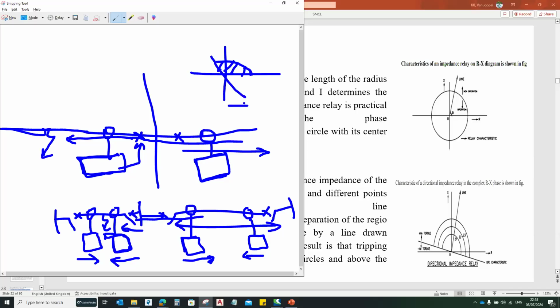The direction element will be set based on your positive sequence values, negative sequence values and zero sequence values. But this curve is starting from the left quadrant. Yes. But the bus is actually located at the zero quadrant, the 0,0 coordinate. Yes. But when we are drawing the graph like a 180-degree angle, then we are taking the left quadrant also.